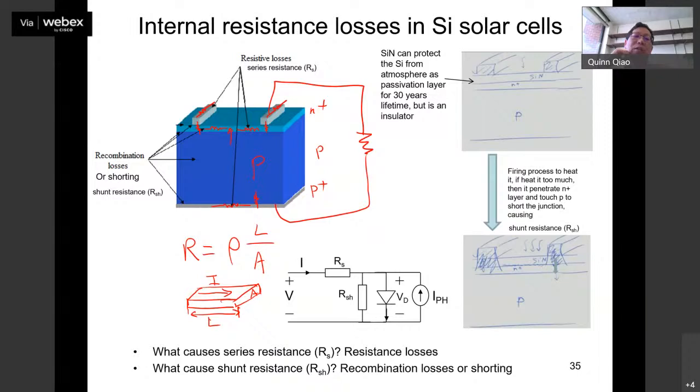And for the contact or the interface, you also want to have a compact interface, and that way you can improve the connectivity of the ITO. Clean the substrate pretty well, so get rid of all the defects, and then you have very good transport for the electron in the series side. So the RS series resistance will be small. These are the basic things people typically consider when they fabricate solar cells.